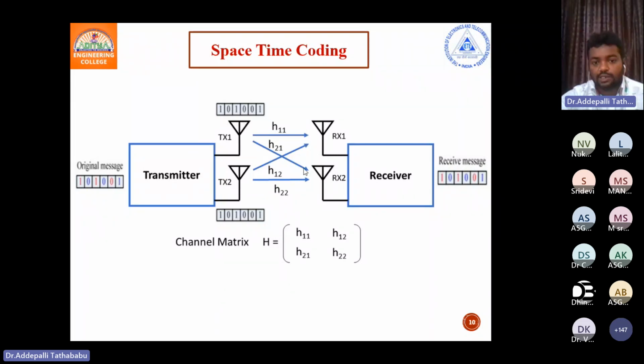the signal is sent multiple times, so the quality of service will improve and reliability will be higher, because definitely you can receive the signal on any one of the paths. That's why one more objective of the MIMO system is that it gives high reliability. That means definitely you can receive the signal from the transmitting side. And quality of service: sometimes the signal will be damaged due to obstacles between the transmitter and receiver. In one more path there are no obstacles between the transmitter and receiver, so we can receive the signal. A better signal we can take, then the quality of service will improve.